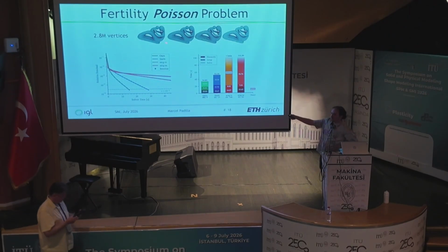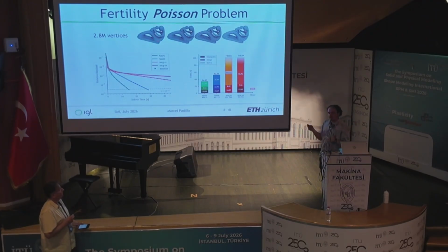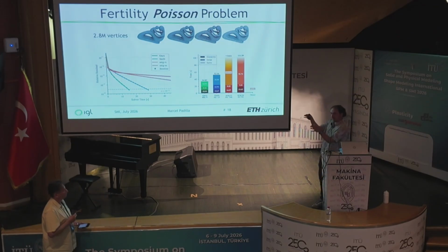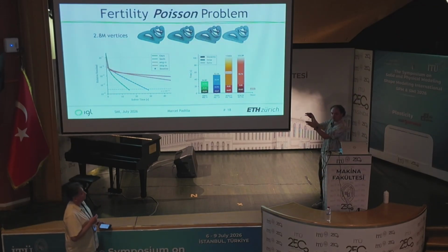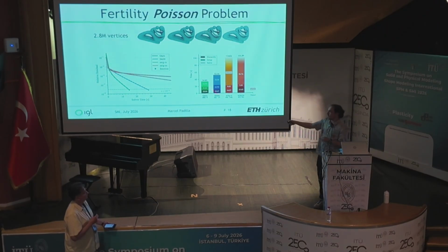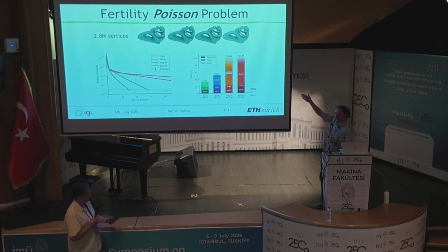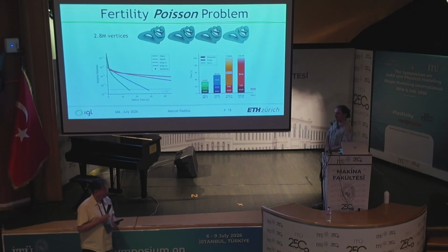So the input mesh is the only input quality tet mesh that we care about. And if that one is broken, then the Poisson problem is broken as well, because then you have these negative masses, or the mass matrix has extremely large values. I trusted TetGen, but if I imagine that we would now break one of these tets, then we couldn't expect any of the solvers to work on this. So my answer would be, yes, by baseline, we have to require good quality tets.